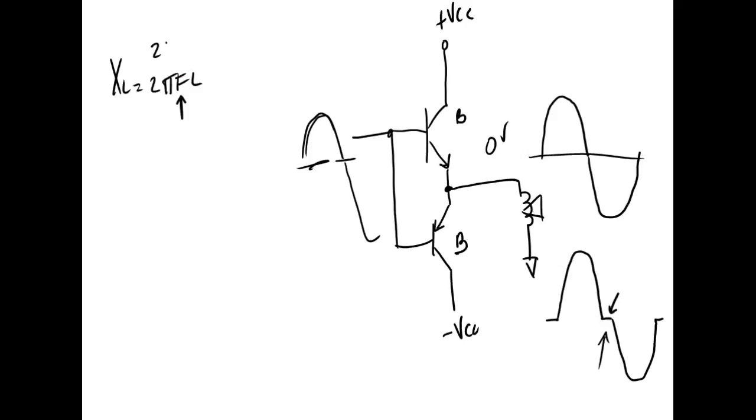What frequency does DC have? Okay. So that means my impedance would be nothing but, if I put DC on the speaker, all it would see would be the R of the wire. That's all it would see. So we don't put DC on speakers. It'll burn them up.